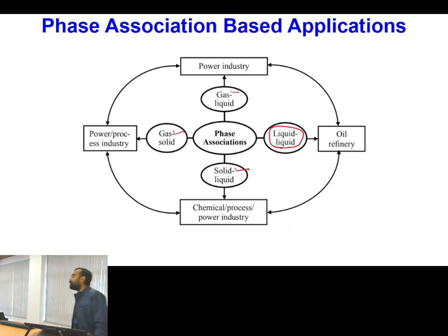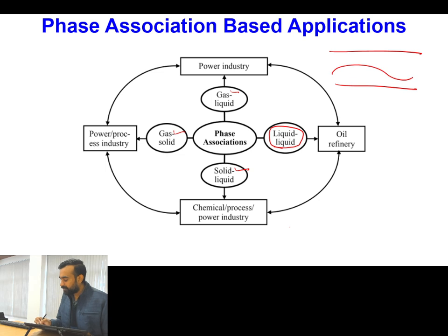So can you tell me what is liquid liquid flow? Two different components of liquid. If these are of immiscible nature and flowing together, that will come under the category of liquid liquid flow. For example, if you take a pipeline and allow water and kerosene to flow together, water will be at the bottom portion and kerosene, because of its low density, can be at the top. However, it will not always be true.